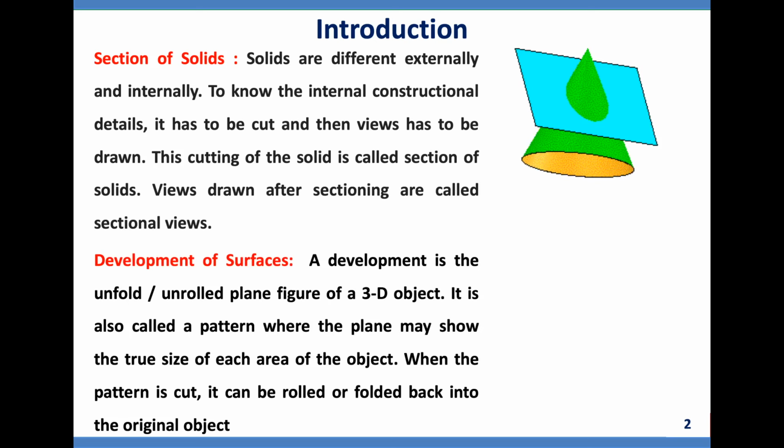Next, development of surfaces. A development is the unfolded or unrolled plane figure of a 3D object. It is also called a pattern, where the plane may show the true size of each area of the object. When the pattern is cut, it can be rolled or folded back into the original object. We'll see how it is.